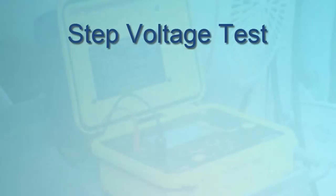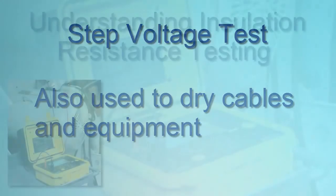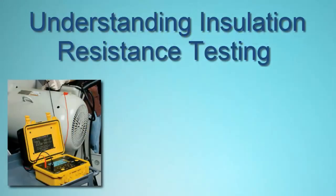Step voltage testing is also often used as a way to dry wet cables or equipment. Gradual voltage steps, applied for increasingly longer durations, can facilitate drying through heating. This concludes our quick introduction to insulation resistance testing.